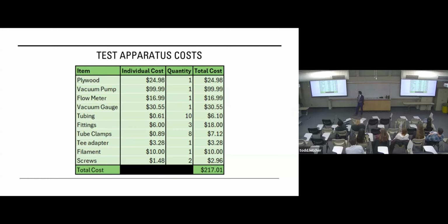We were able to shave the price down in some areas like the flow meter, where there could be an extremely precise application for a lab, where we were just trying to get within the range of about 20 liters per minute for our inhaling rates. For reference, at normal breathing rates, the average human takes in about 6 liters per minute, whereas when you are inhaling for a nasal spray, you're taking in about 20 liters per minute, based on the data that we saw in the research papers, where they had female participants ranging from about 17 to 23 liters per minute.